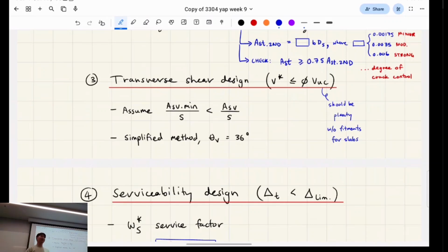There's another concept that's not covered in this course, but it applies a lot to slabs. If I stab this pencil through, that's called punching shear. It happens a lot between columns and slabs. It's like a hole punch, or like if my fist punched through this towel. What happens is the column literally penetrates the slab, and then the whole slab falls through, as if the column was like the pencil. So there's actually two types of shear actions that happen on slabs. But we're designing specifically for the transverse shear, which is the ripping.